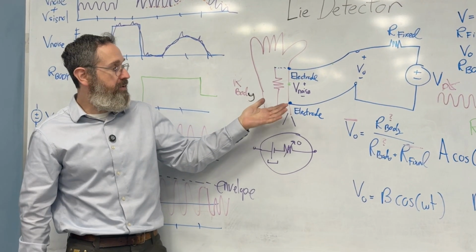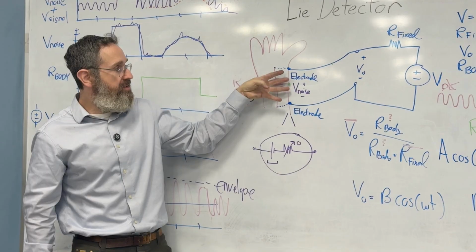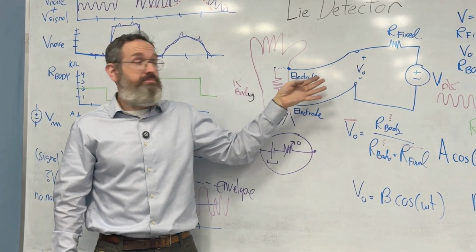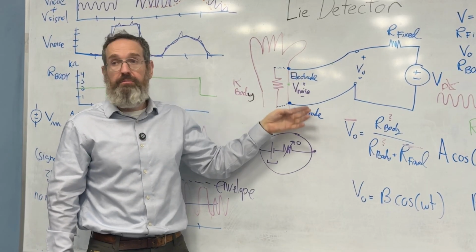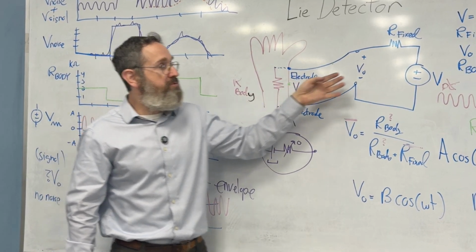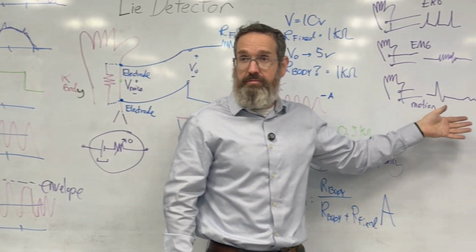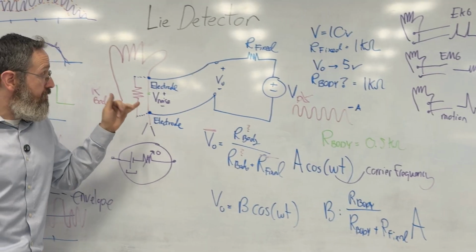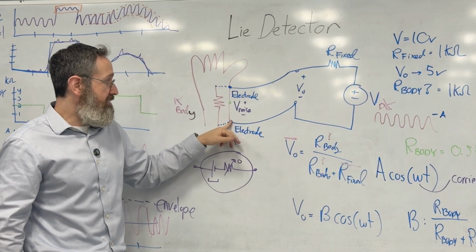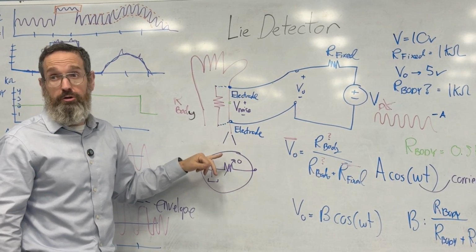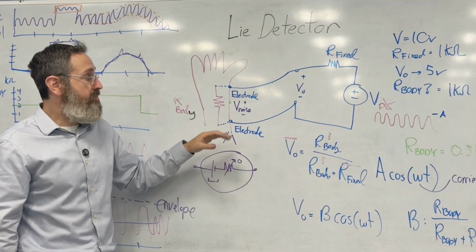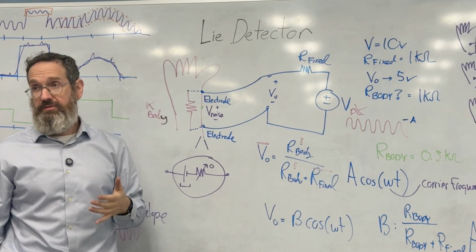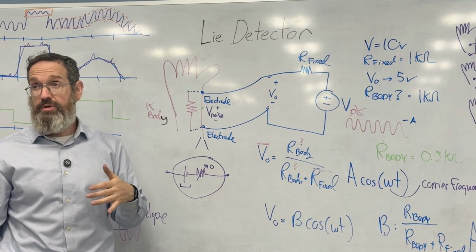So what I was trying to explain is that one reason you would have noise of an electrical origin is because this is exactly how you would pick up biopotentials. And so these biopotentials should be coming through, right? On top of that, all the other types of noise that would be introduced at the electrode are also present. And so that's why doing this approach with DC might be very difficult. All right, that's one reason, if that makes sense.